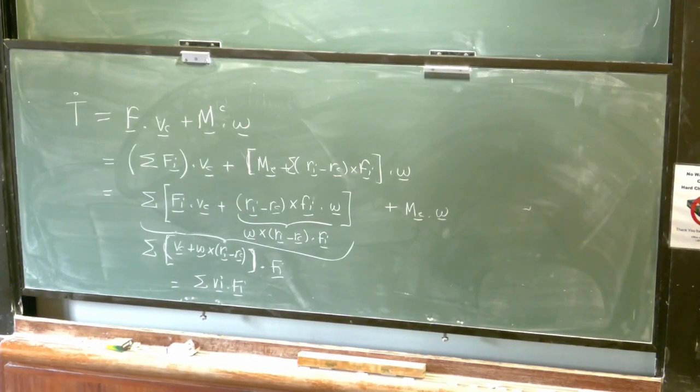Yes. Why? But there is a reaction force at O acting on the plate. But it's workless because why? It's acting at a point with no displacement, zero velocity. So the only force doing work on the system is which force? The weight, which is conservative, so the energy of the system is conserved.